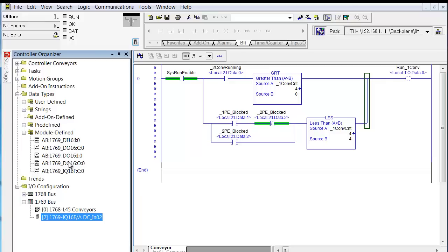For that output card that we did have in slot 1, local 1, these 3 tags, structures, these are classes of objects, and instances of each of these was in place in the virtual I/O configuration in memory to represent that output card as far as its data goes. Because remember, the data in that part of memory will match what is sent to the output card for configuration, will match the structure that you send data to control outputs, and it will match what comes back from that output card back into memory as far as input information goes.